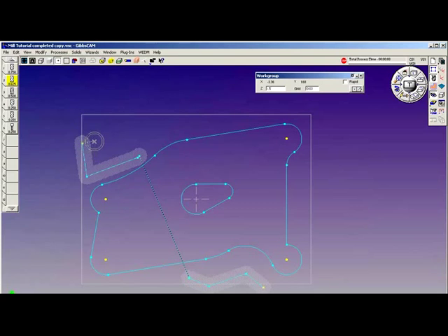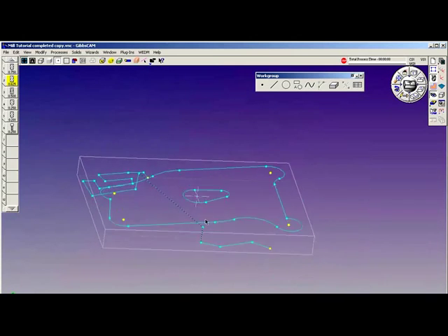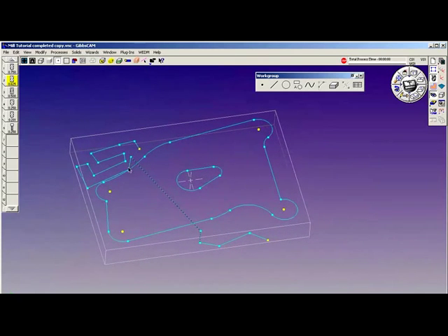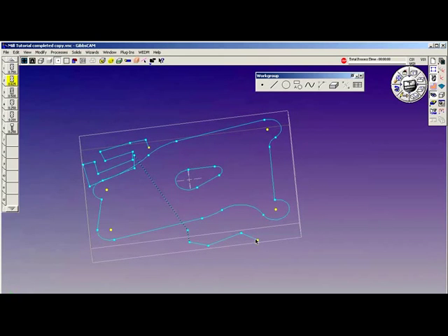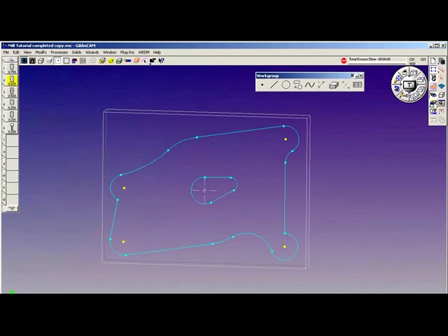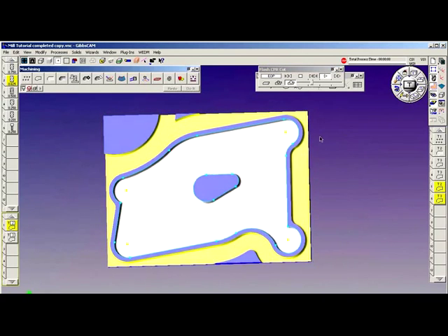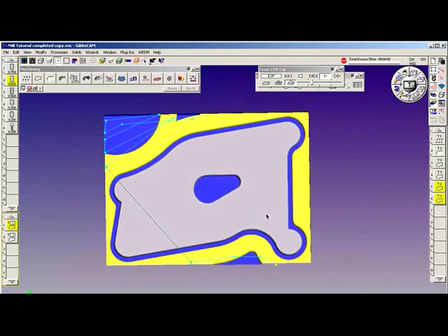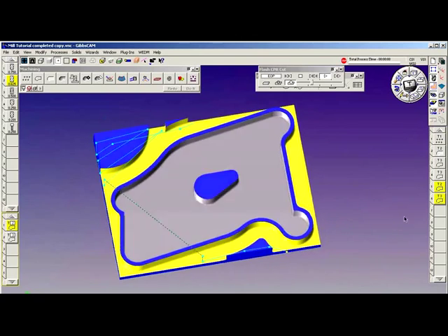Watching my cutter do the metal removal with the gray portion that appears on screen. All right. So as you can see, there's the rapid moves up and over the part. Now machining here, rapiding up, rapiding over, and then feeding down and machining that portion of the part. All right. So that's the next operation. I'm going to render it once again so we can see what we're doing. And then we're going to remove that geometry using tool number 2.